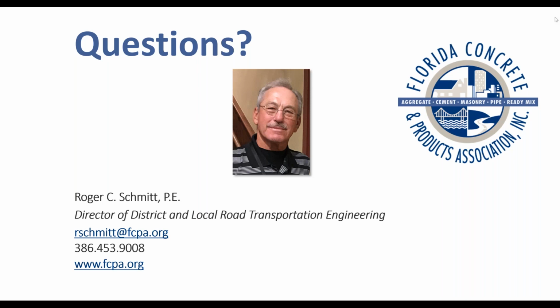Follow up on that: is the curb actually considered as edge support, considering the fact that the actual loading moves away from the pavement edge? You can consider it as edge support if you have tie bars from the curb and gutter into the concrete pavement. It has to be tied. They use a lot of tied curb and gutter in the northern states.